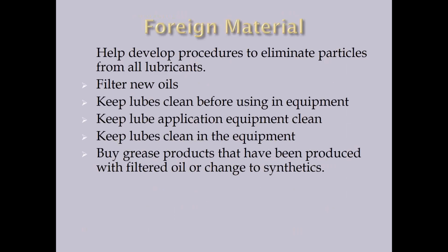So for material, here it says help develop procedures to eliminate particles from all of our lubes. Filter your new lubes. They are not clean. Keep your lubes clean before putting them in the equipment. So once you filter your new lubes, then we've got to keep it clean all the way to the equipment. Keep your lube application equipment clean. One of the things we did at our plant, we bought oil-safe containers and got the guys using them. As the oil-safe containers started looking dirty, we found out we could make them look brand new and clean them in a dishwasher.